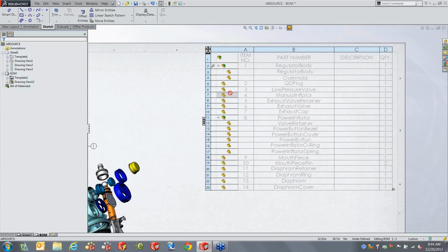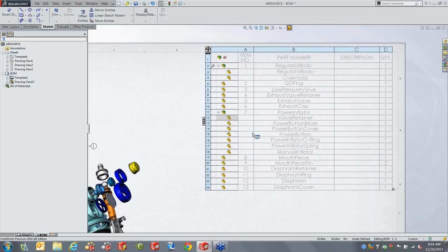Most people are probably aware of that. But I can also drag a component into a subassembly and actually place it as if it was modeled part of the subassembly. It just shows you that you've done some reorganization in the bill of materials. But I think getting into this stuff will help people create a bill of materials that's accurate enough to take that data out as a CSV and take it into another business system or utilize it a little bit better.